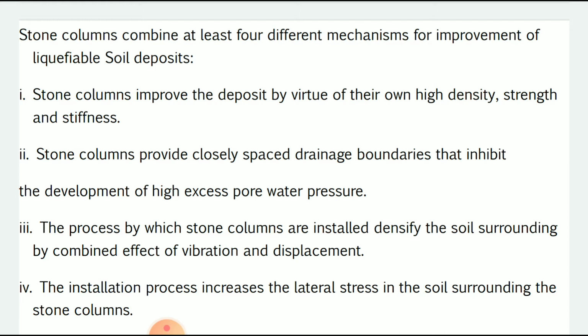First, a stone column improves the deposit by virtue of its own high density, strength and stiffness. Then it provides closely spaced drainage boundaries that limit the space available for the development of high excess pore water pressure.